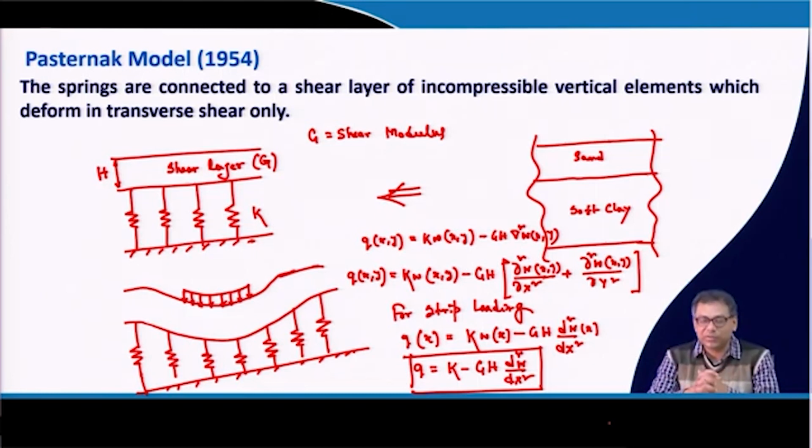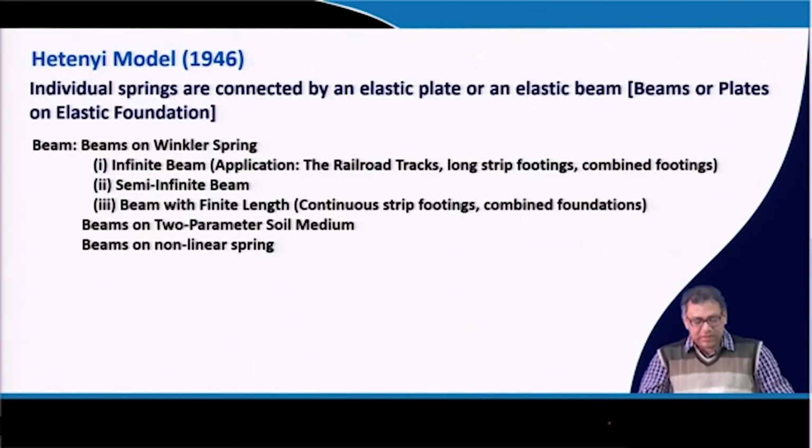So if you replace the spring with a spring and dashpot, then you can incorporate the time dependent behavior into these models also. The connectivity issue is solved, your deformation is not only confined to the loaded region, you get deformation outside the loaded region, and you can incorporate the nonlinearity and the time dependent effects. So all these effects can now be incorporated in these models. Now, the next model that I will discuss is the Hetenyi model.